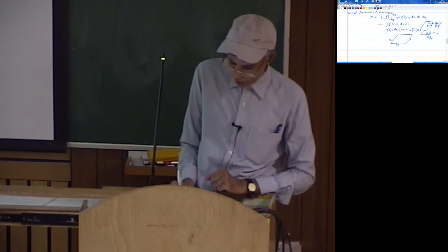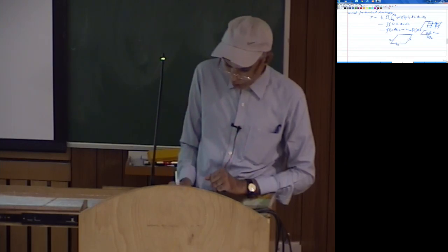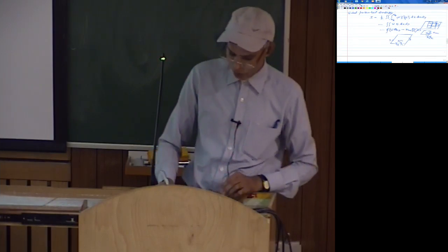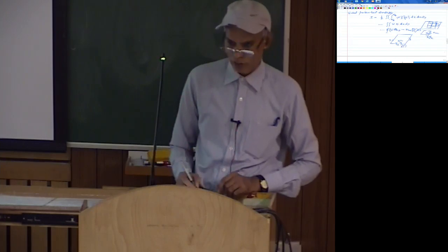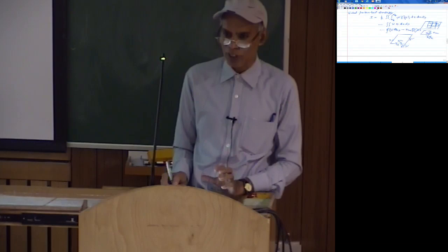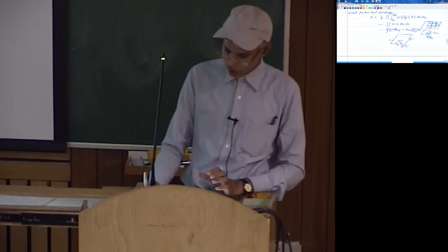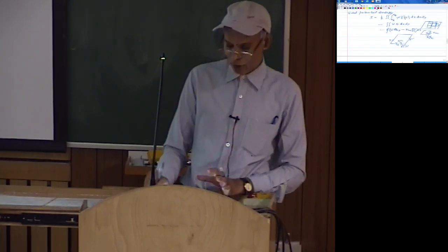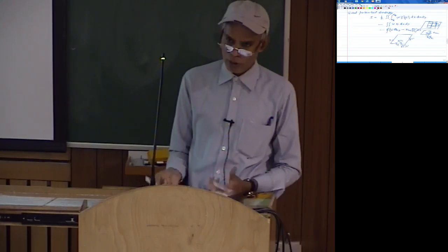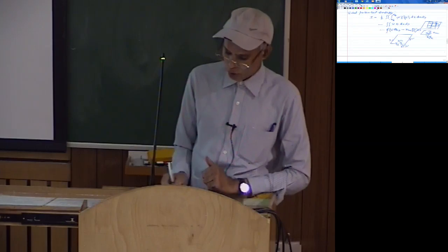If you recall, we said that the normal is initially like this and then rotates like this. So this is del w by del x, which is the rotation about this axis. You see here that m x x and del w by del x are in two opposite directions. So m n n and del w by del n would be of opposite sign. The work done is negative, the potential is positive, so that is why I am putting a minus sign.